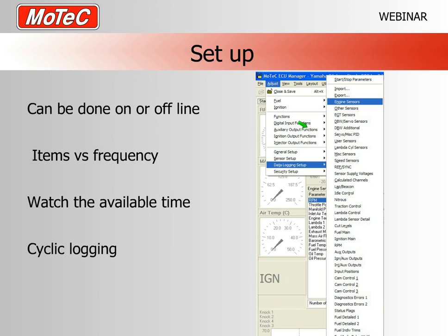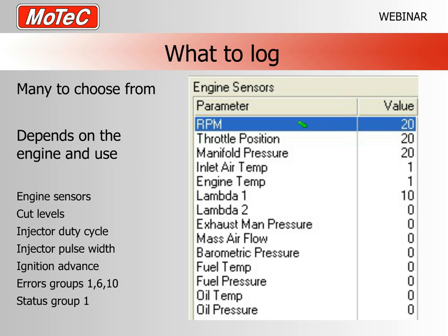So the logging, when configured normally, will always get the last available, in my example case 20 minutes. So you need to be careful about how you use the vehicle or how you do your testing, and think about how much logging time you've got.